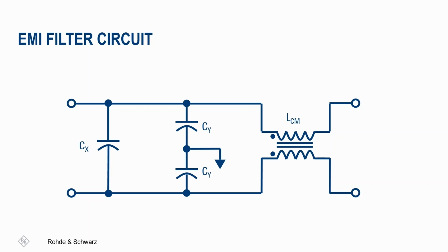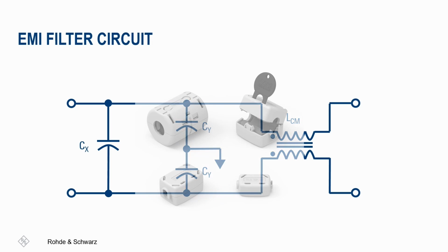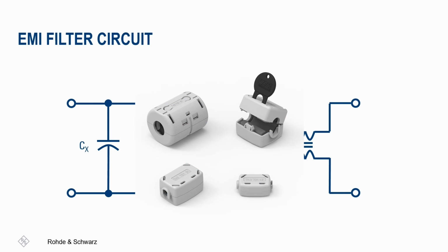Let's delve into understanding how an EMI filter circuit works. There are different approaches to handling conducted emissions. It can involve a circuit designed as part of the power input of the system. Alternatively, in cases where a product has failed in the EMC lab and didn't account for an EMI filter circuit, a quick fix can be achieved with ferrite clamps. While ferrite clamps offer a fast and effective solution, they may not be cost-effective if every inlet cable requires one.